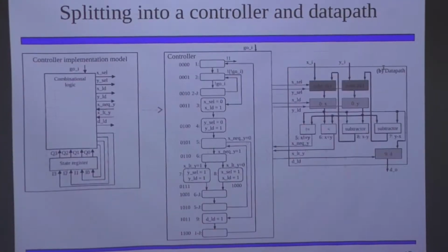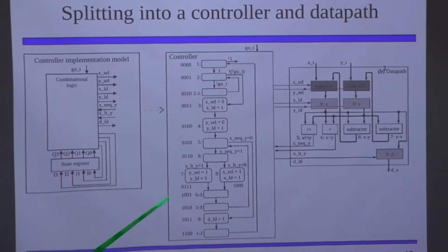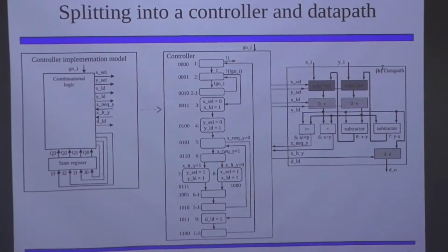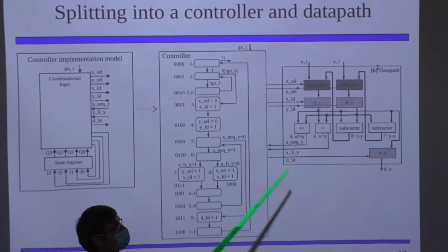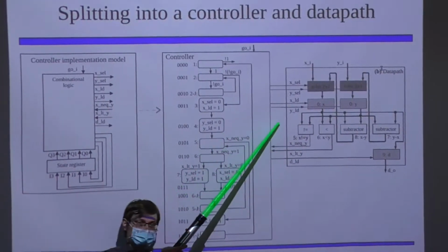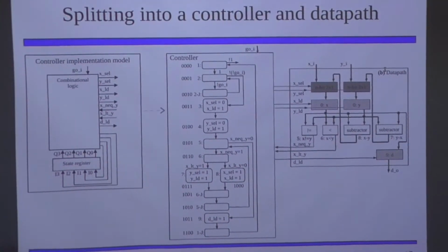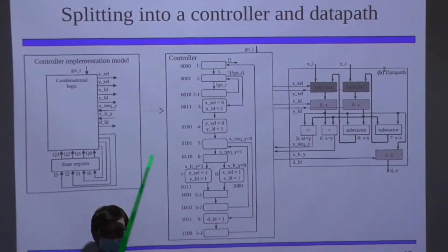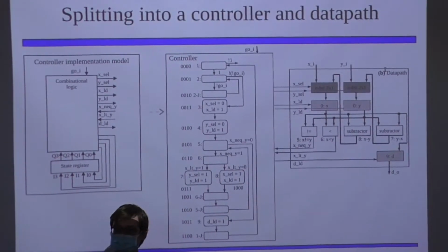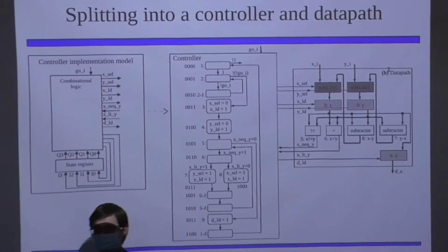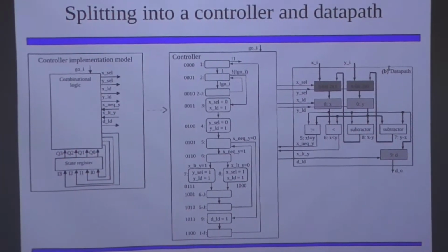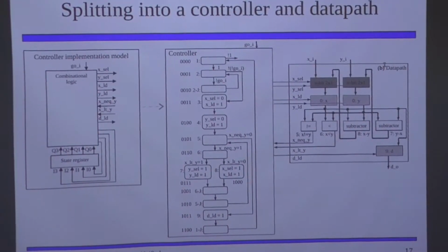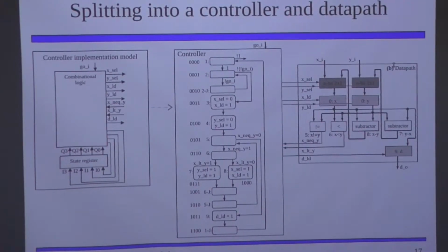The same is not true of the selection of the selector multiplexers. The selector signals to those don't actually matter in cases where the register isn't being loaded. So at times other than during register loading, we actually don't care what the selector signal is. Make sense? Good? Any questions so far? Can I get a thumbs up? Awesome.